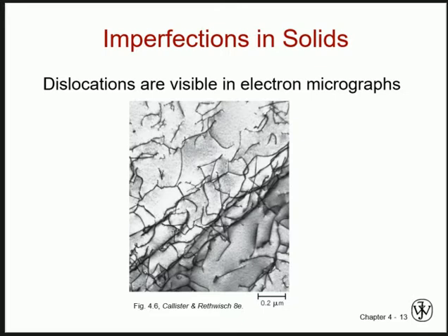Okay, and then there will be specific planes on which the atoms move from one place to the other. Next, when atoms are moving within a crystal structure during deformation, usually it's not a single atom which moves from one place to another. Rather, it's a series of atoms, a line of atoms which move from one place to the other, and these lines of atoms are called dislocations. These lines of atoms called dislocations tend to move together in a coordinated way in a particular direction under the influence of the force.